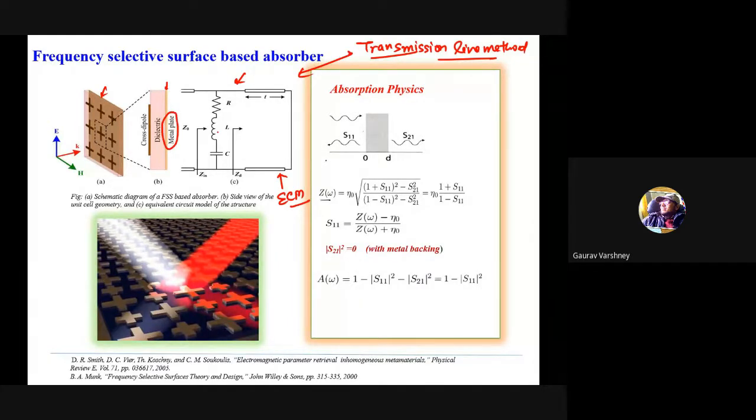If we are talking about the metal plane, and if we see the basic concept of the transmission line, here we can use a transmission line, and this is the length of the transmission line. This is the source VS, and there is some current IS. Some internal circuitry will be there, you can understand RLGC, R, L, and G, C. Fine, so this is the basic structure of the transmission line, and at the load end, this is ZL.